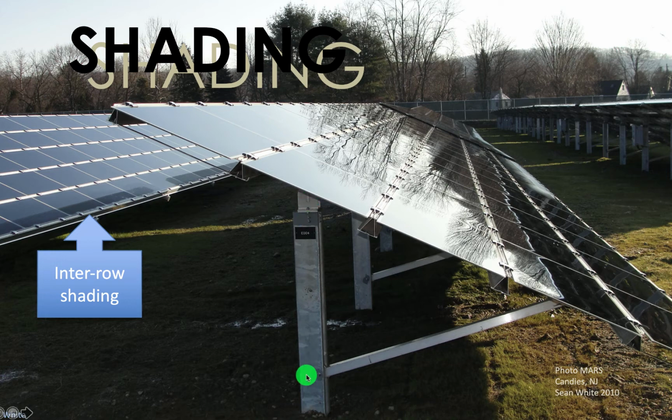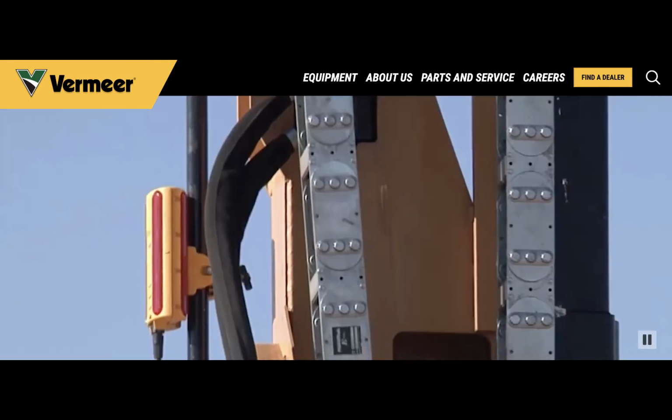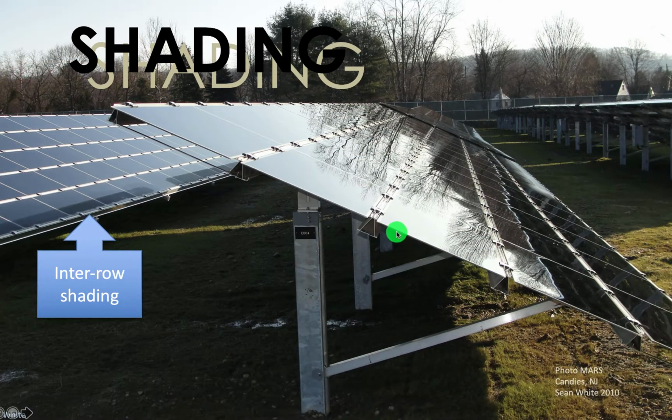You can see that we have steel driven into the ground. It's driven into the ground like a nail. It's called a pile. Pile driving is the main way that utility scale solar farms are installed. These particular modules here don't have frames, so they're frameless. They're more likely to break, but they don't have to pay for frames. They have to have special clamps with gaskets, and sometimes they're called laminates because they're made with a thin film laminating process, substrate on glass.